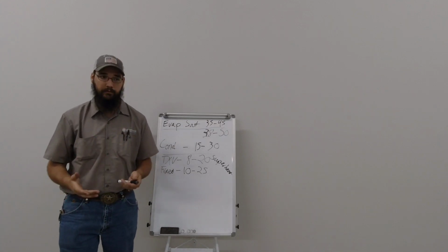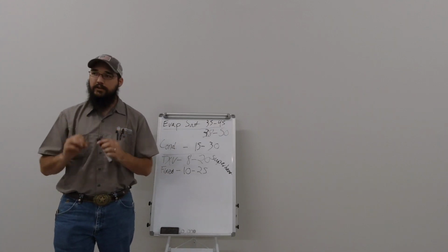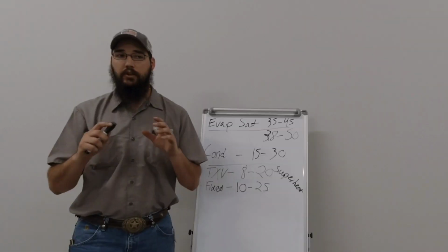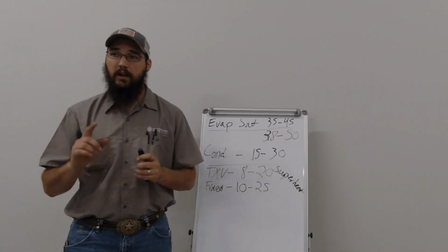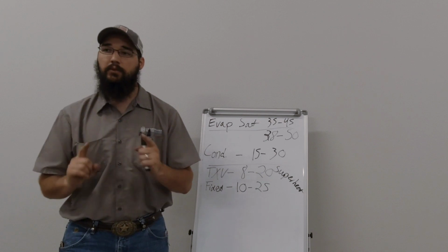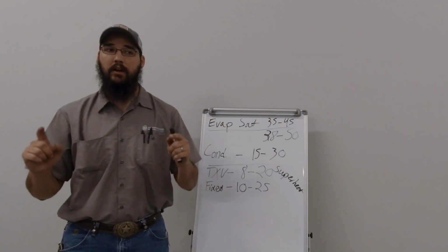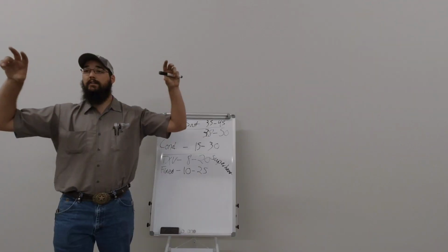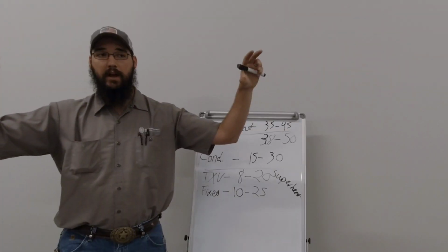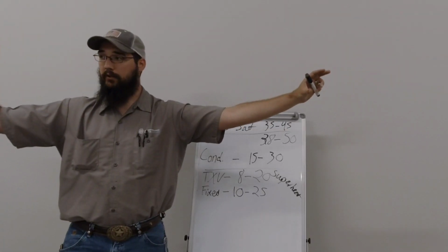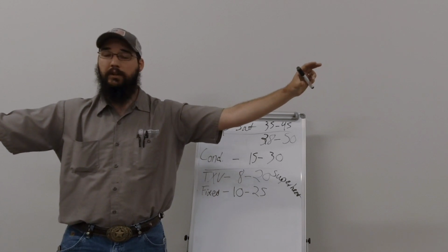We'll start with something more simple. When you go to calibrate and adjust that system, you've got to do it a very specific way because that system stages in different ways. And you've got to make sure that those TXVs are set accordingly. Trane ends up putting one valve per side of the coil, and they split the load between 2 valves.